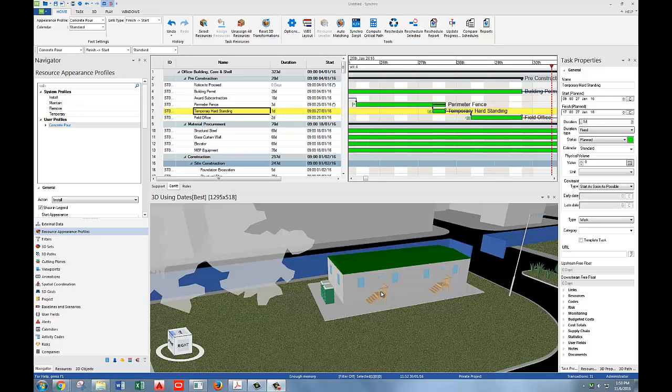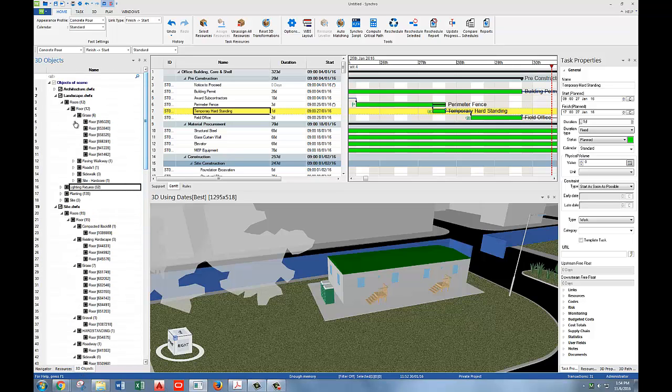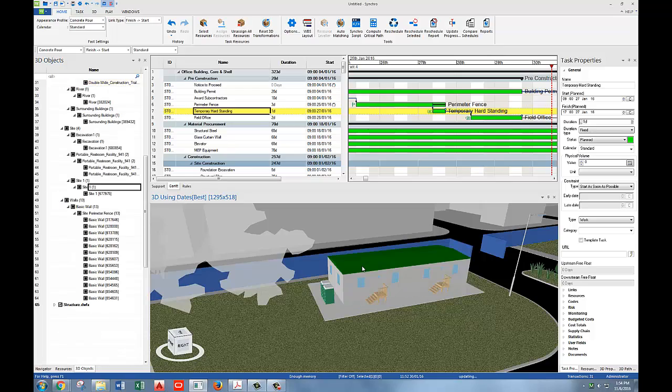The examples that we've just gone through are exactly that. They're just examples on how to link. There are actually many ways that you can go about linking 3D elements to activities in your activity list. Depending on your individual workflow, you'll probably do things a little bit differently, just depending on what you find easiest. Remember that there are many ways to select objects, so going to your 3D objects over here, you can select items through the tree. You can select items physically in the 3D window.